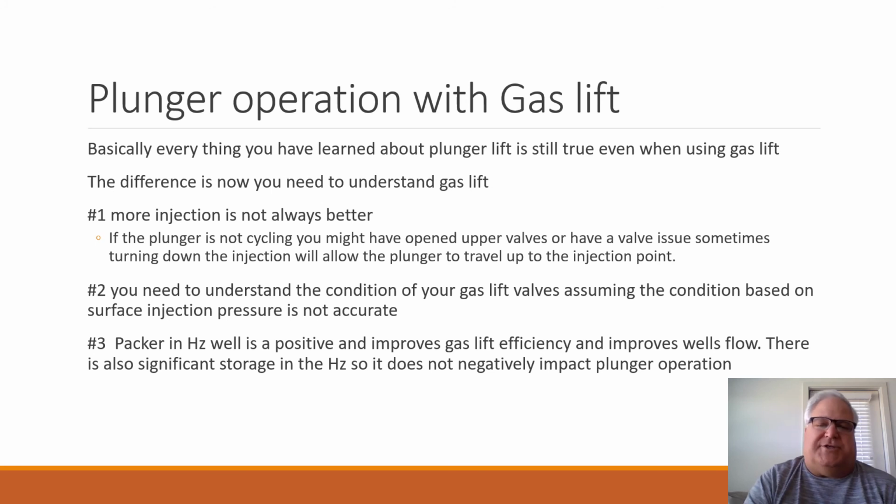You need to understand the condition of your gas lift valves. So many of these wells, people come back to us and say, hey, I tried a plunger lift, it didn't work with our gas lift. And, looking at our pressures at surface, we think that we're at the bottom, but that surface pressure does not tell you really what's going on downhole. Most of these wells are multi-pointing, or they have a significant issue uphole that could be showing a lower pressure at surface, which would indicate that you're lower where you're not.